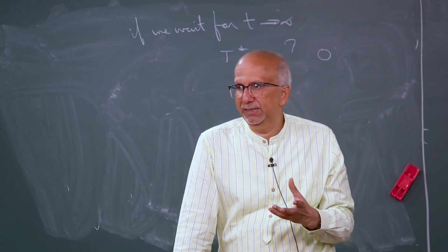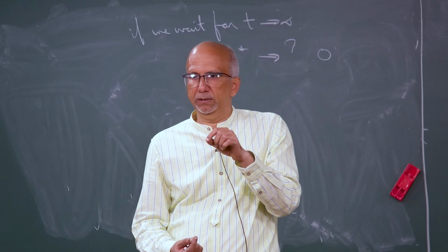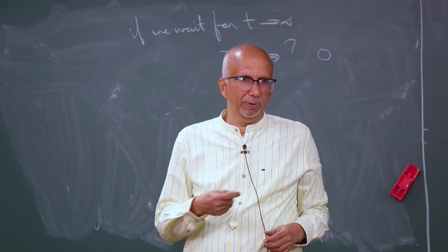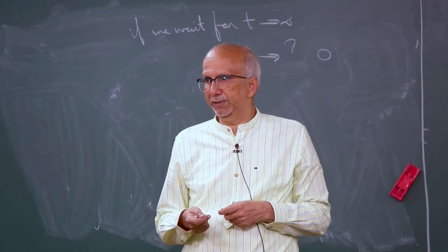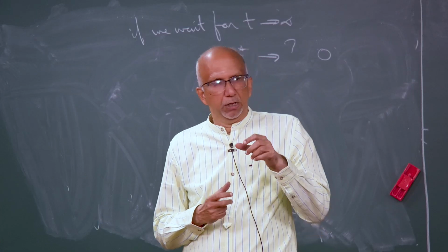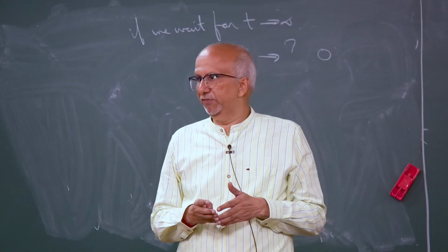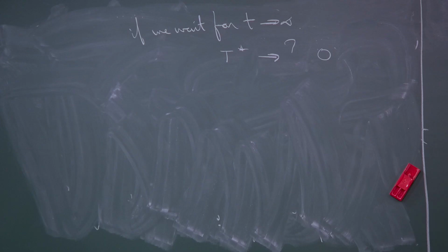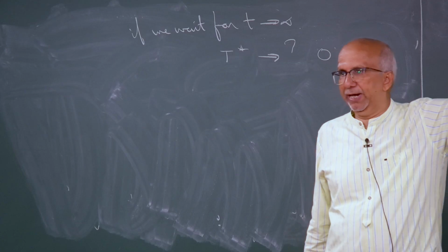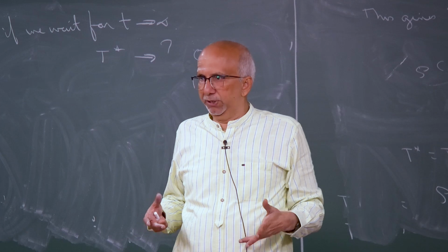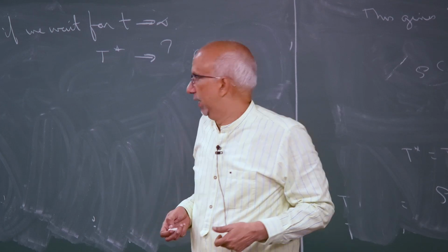One way to physically understand that is, suppose you are passing some electrical current, and because of, let us say, Joule's law of heating, there will be some resistance in the solid. So, heat is going to be generated by Joule heating, which you have studied in physics. If this source is uniform everywhere, then there is going to be an additional source term here, which I have to include. If I include that source term, that is the equivalent of my dP by dx which I had in my fluid flow problem. In the fluid flow problem, my dP by dx was my non-homogeneity which was driving the flow. So here I am saying we need a heat source